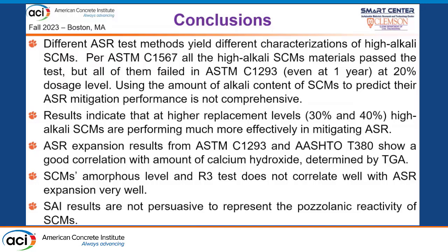Also, using the alkali content of SCMs to predict their ASR mitigation performance is not comprehensive. The results indicate that at higher replacement levels, the high alkali SCMs perform much more effectively in mitigating ASR. And the ASR expansion has a very good correlation with the TG result, but does not correlate very well with the R3 test and amorphous level.